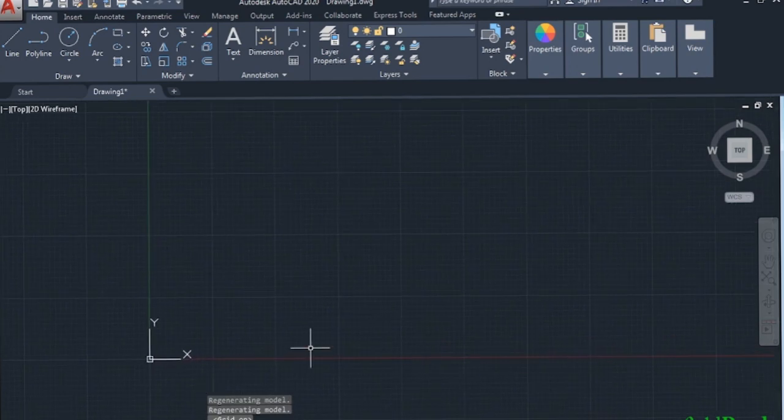Now if we do not want to set up units every time we start a new project, we can save these software settings into a template. A template is a file that stores the user-defined units, software UI layouts, sheet layouts and many more settings in it, so that we do not have to set the settings again and again for every project. As of now, we are only going to save units and grid settings into this template file. As we progress along the course, we will keep on adding more settings to this file.